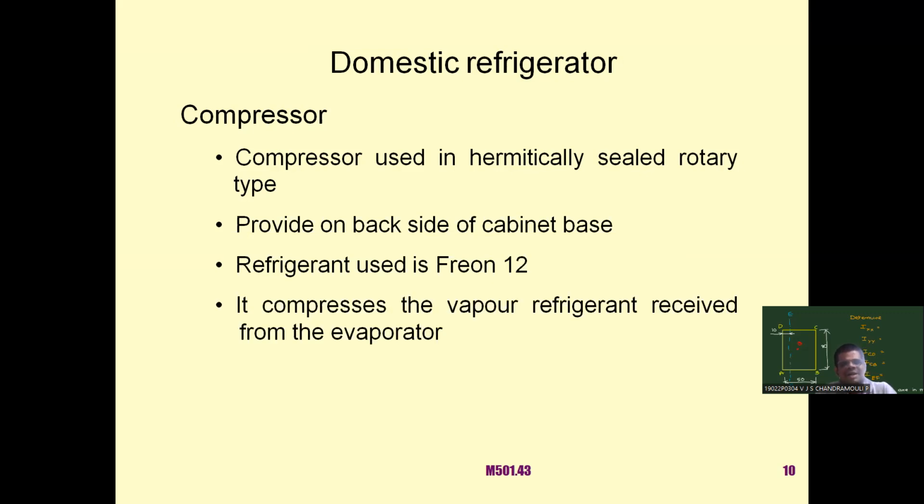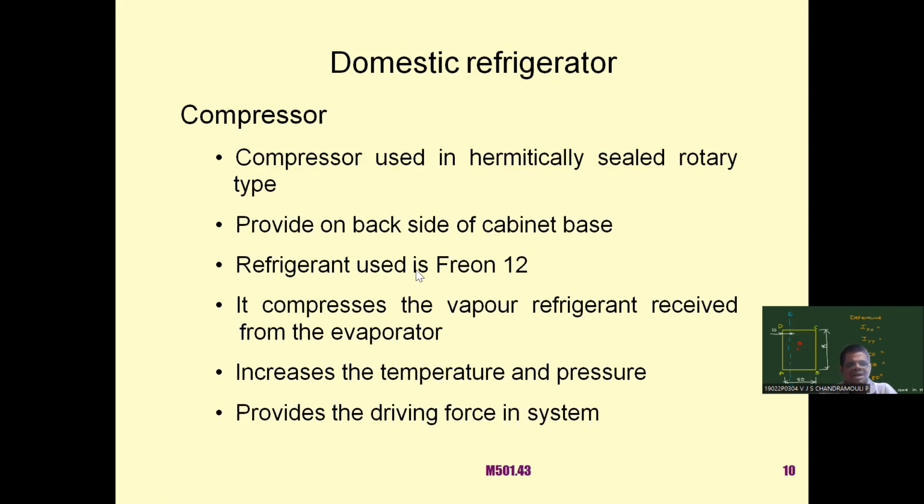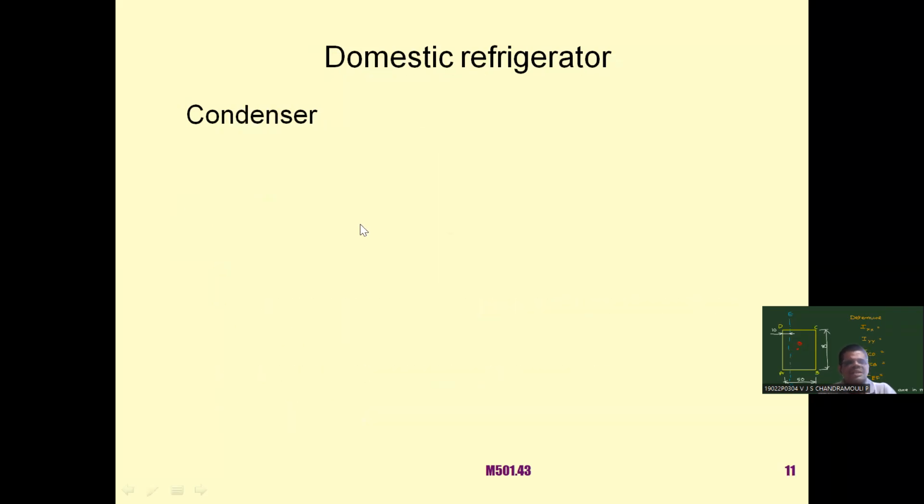And the compressor compresses the vapor refrigerant received from the evaporator. We have already discussed that, and it increases the pressure and temperature, and also it provides driving force into the system. So it drives the refrigerant throughout the system. That means it pumps, it ensures the flow of refrigerant through the system, right? So that is about the compressor.